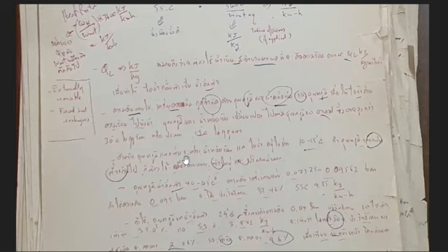So we want to reduce the amount of water droplets as much as possible. Anyway, the temperature that we can increase is limited by the material in the turbine, because we cannot just increase the temperature. We normally can increase the temperature up to around 500 degrees Celsius, something like that.